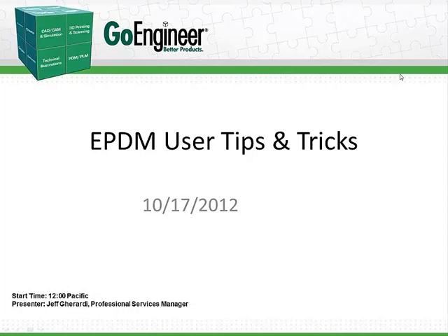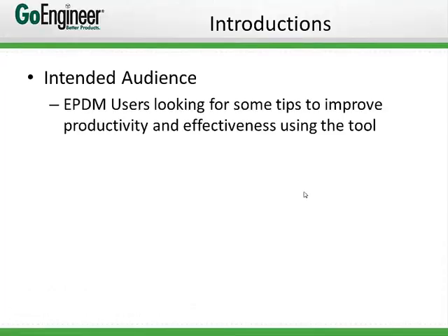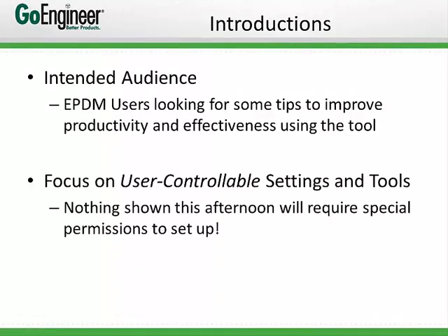So this afternoon, we're going to be taking a look at some things that we can do in Enterprise PDM to enhance our personal productivity, and they're things that we can do all on our own without having to go to the administration tool, without requiring special permissions in order to set up. These are all going to be client-side settings that we can take advantage of and put in place on our personal machines.